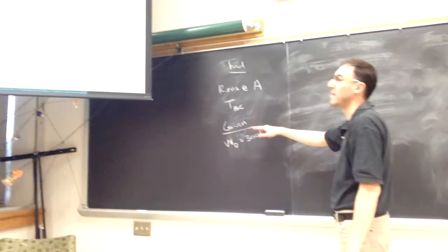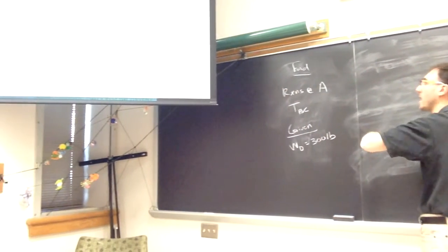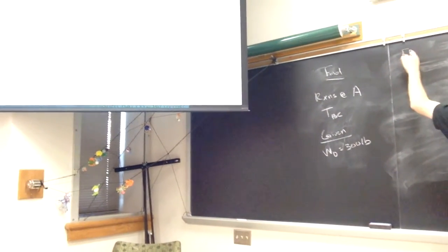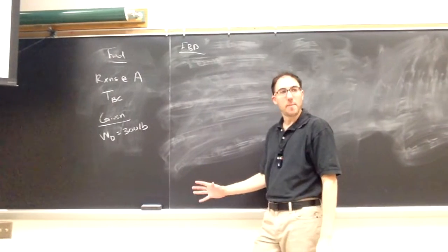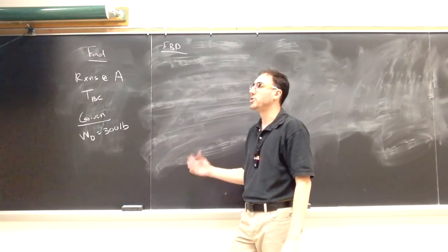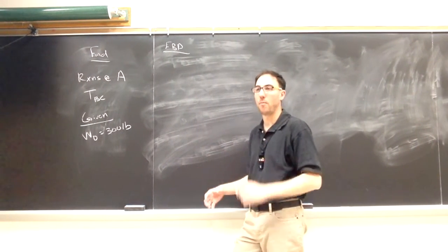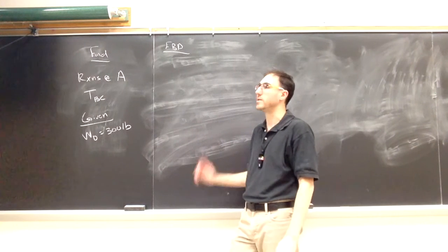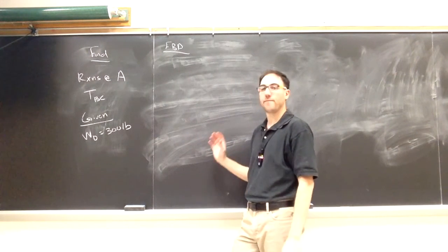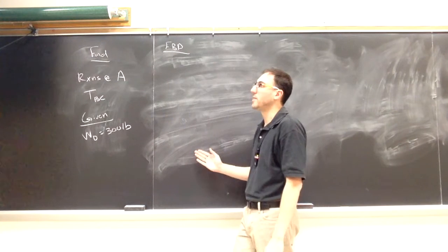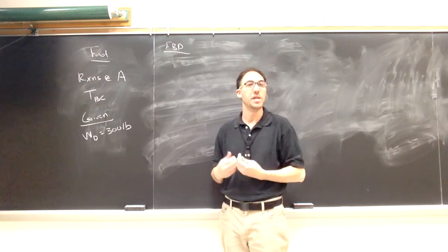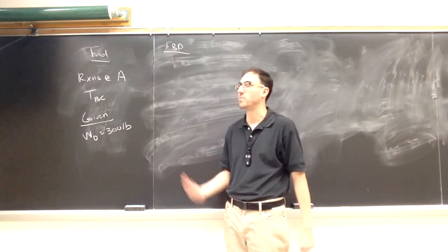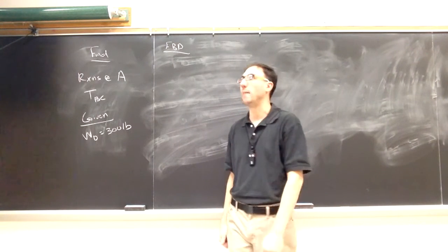So that's the extra information that is not in the diagram they gave us. The free body diagram step, again, this should be kind of the toughest step once you get the equation writing down and the solutions down. We need to first pick what is our object of interest that we're going to isolate from all of its connections. And then we have to draw on there what those supports, what those connections did to our object.